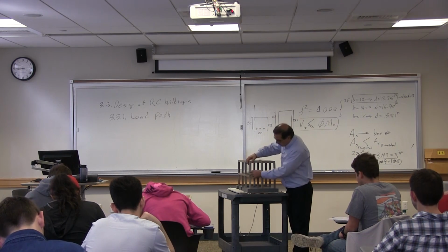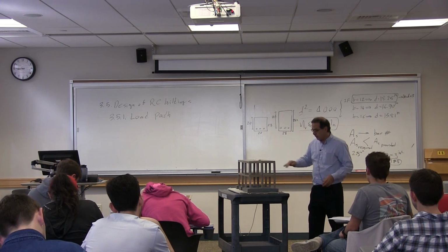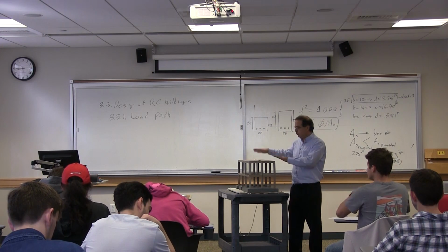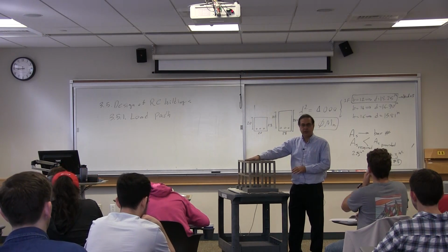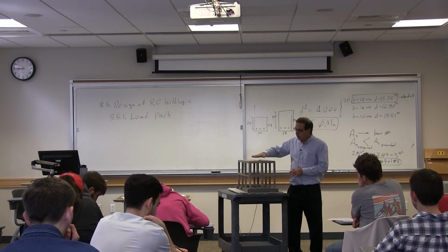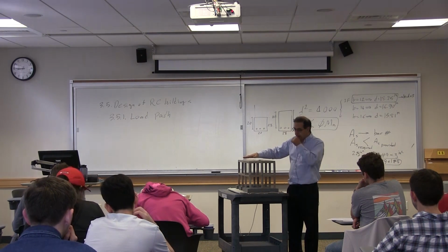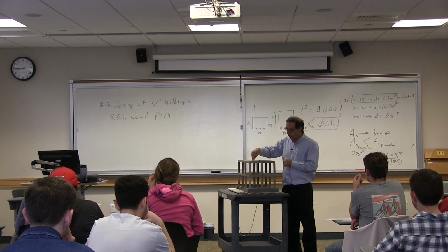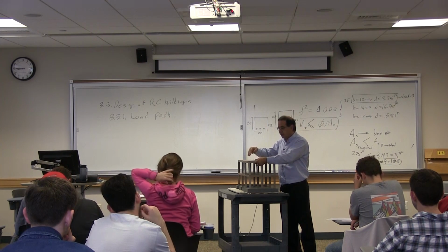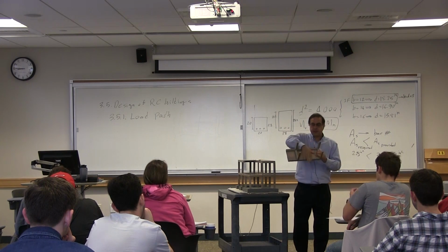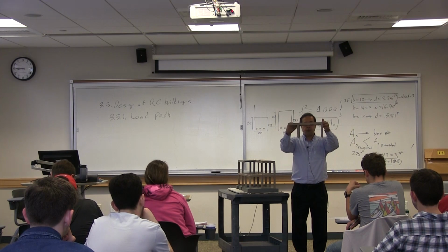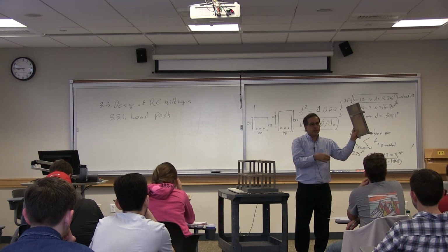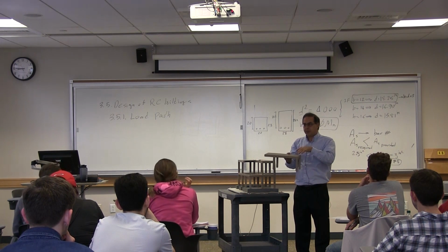That is, how does the load transfer from the point of application? Let's say we have some load here. This is the roof and the snow comes, and then we want to know what happens to this load. The load will apply to the floor. The load applied to the floor will transfer to the beams. So this is the floor. I applied the load. There are beams, in this case on all four sides. The load will go to the beams.